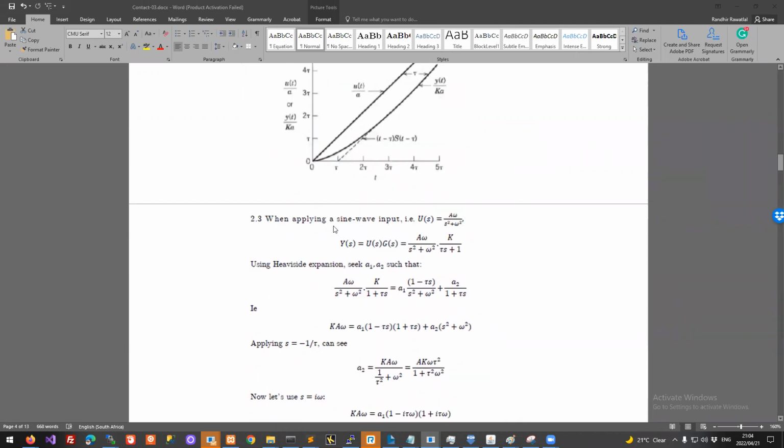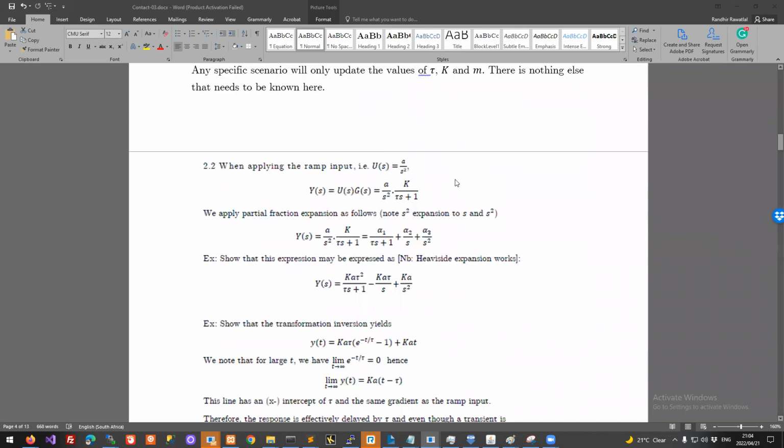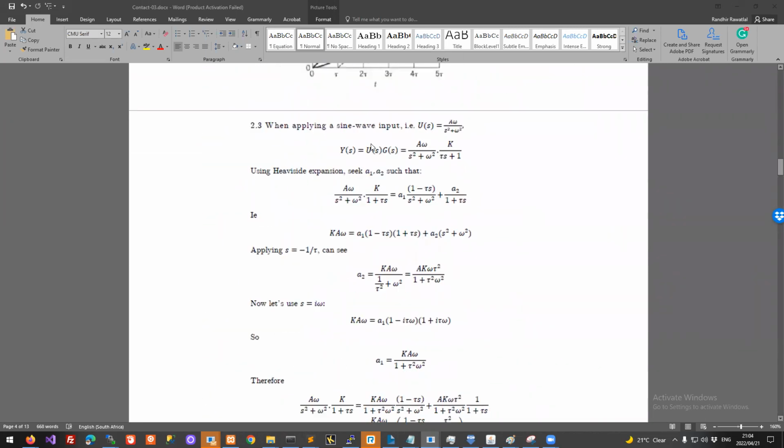The reason that we are looking at the sine wave is that we'll find that if we apply sine waves, we learn a lot about the control of the process. So it won't be clear right now why this is important. In fact, it is much more important than these steps and ramps and so on. In fact, this whole section is frequency domain dynamics. Frequency, because we are applying a sine wave that has a certain frequency. So we'll see later on, there's a very good reason to apply sine waves. And so that's why this particular form, a sine wave, is important to understand.